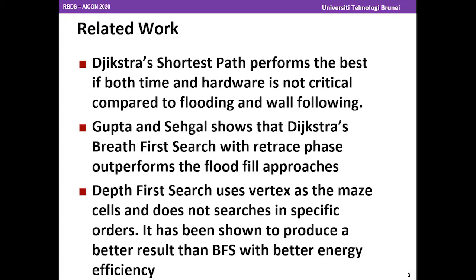However, if both the time and hardware constraints are not satisfied, they showed that flood fill is usually preferred compared to wall following and A-star. Flood fill is capable, however, it can be very energy inefficient because you need to go through all the networks and then come back with the optimal path in the maze.